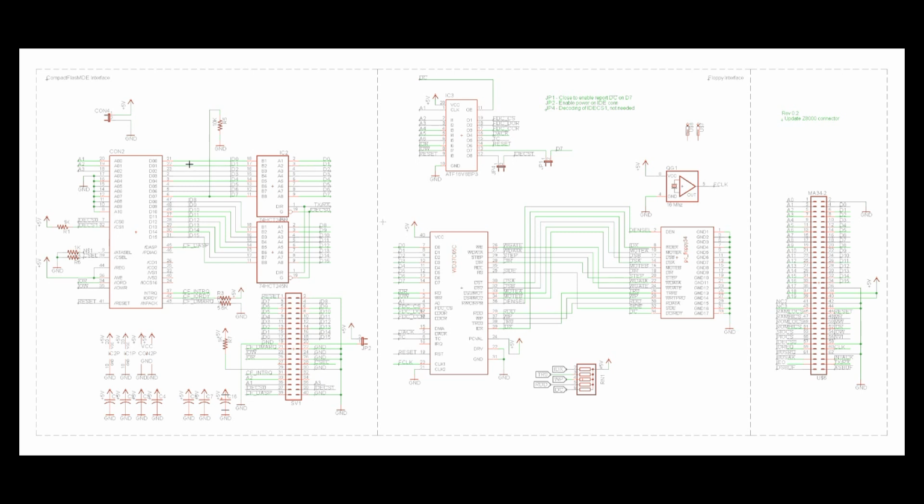They would pull the bus down. If the card was installed, the thing would become unreliable. So ever since then, I've started putting buffers in so that we only connect the CompactFlash socket when we're actually reading or writing the flash, and it cannot interfere with any of the other peripherals in the computer. So that's this buffer.